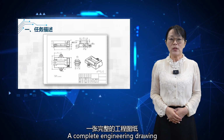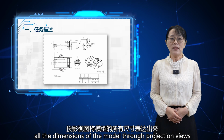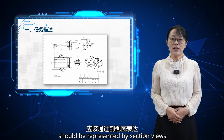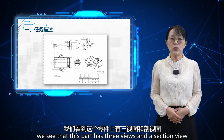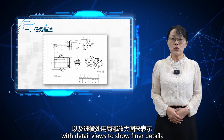A complete engineering drawing must express all the dimensions of the model through projection views. An internal part should be represented by section views. Therefore, we see that this part has 3 views and a section view, with detail views to show finer details.